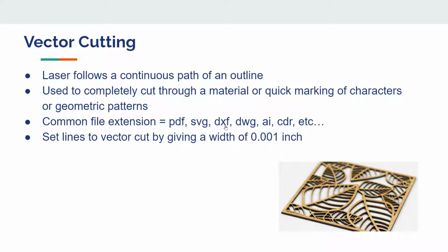Now with our laser, the way you tell it that you want to cut a specific line is that you set that line width to 0.001 inch. And this is something we'll go over when we do the in-person training.